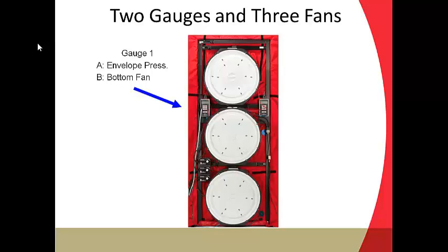If it's an envelope pressure, if it's measuring a building with respect to outside pressure, we call that an envelope pressure. It could be an interior pressure, where you're monitoring interior pressures to make sure they're within 10% of the induced pressure. We call those interior pressures, and then that'll show up on a report to document that all your interior pressures were within 10%.